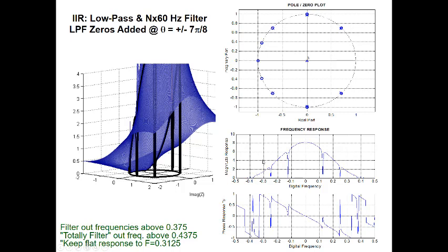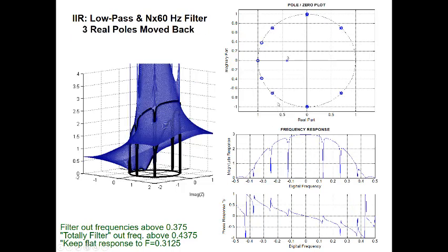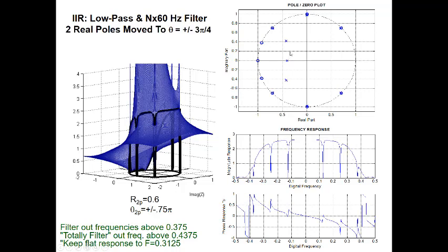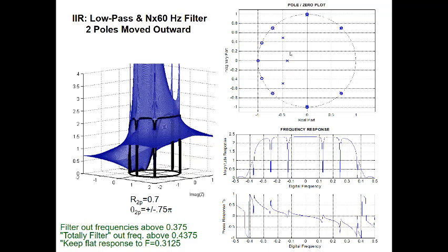But I'm going to need to push things back up over here at these frequencies to get back to the passband that we wanted to preserve certain frequencies. And so for that, maybe we'll bring some poles out that way to try to bring up that side of the rubber sheet. To balance things out, we're probably going to do better by splitting those off closer to the zeros. Maybe move them out a little closer.